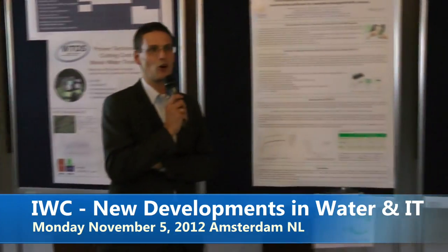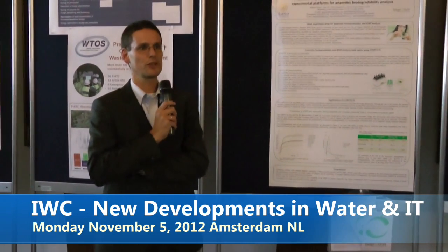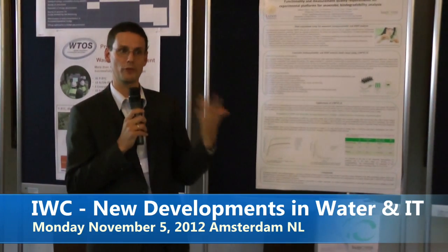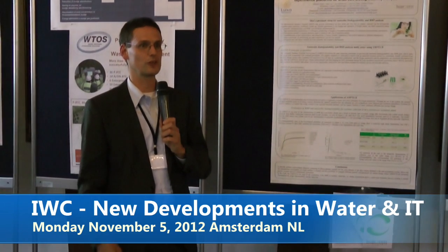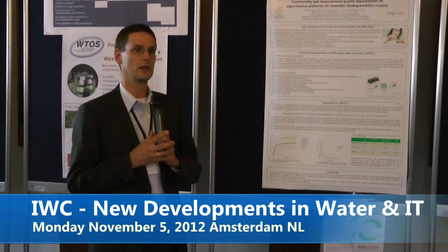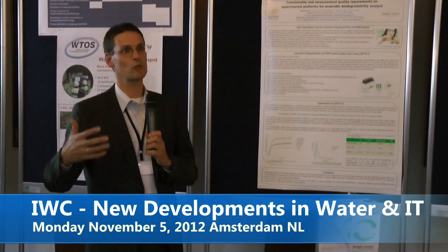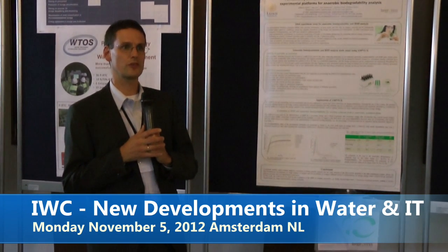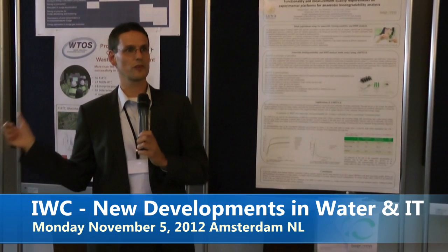I agree, savings are always related to the jump-off point, meaning where you are coming from. But just an example here from Southern Water shows, which was, in my opinion, at least for the UK standard, a very high level of control automation already, because for 4-stage processes, they had a very good working DO control in place. And what we added was an ammonia-based adaptation of the set point. And we were also surprised that we were really able to gain 25% savings.